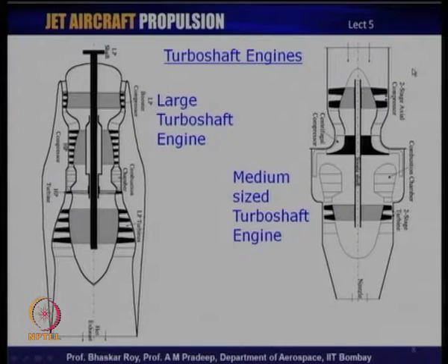The rotors also typically run at very low speed, like the propellers, quite often even lower speeds, maybe less than 1000 rpm, and these rotor sizes are much bigger than that of propellers. The rotors can be as big as 8 to 10 meters in diameter, and as a result their rpm would have to be somewhat restricted for various structural and aerodynamic reasons connected with the rotor motion.